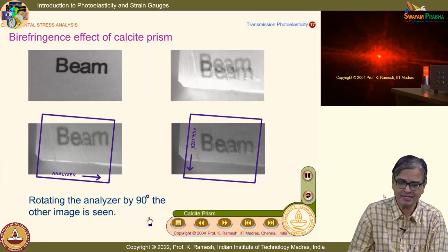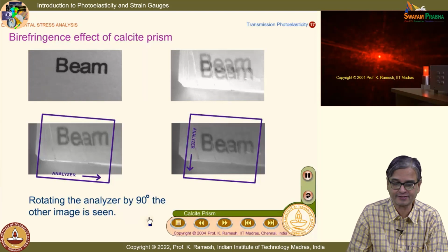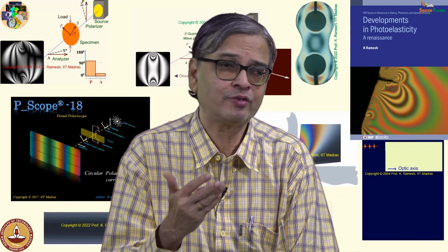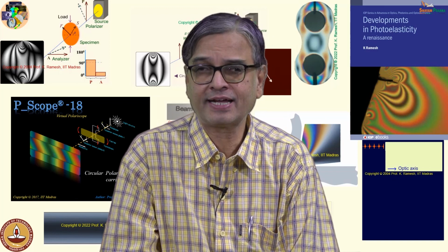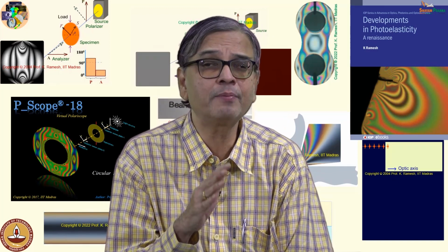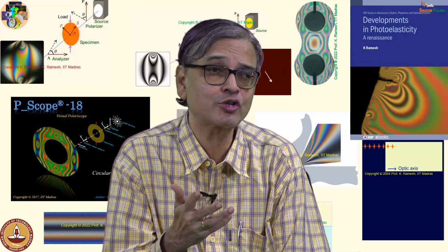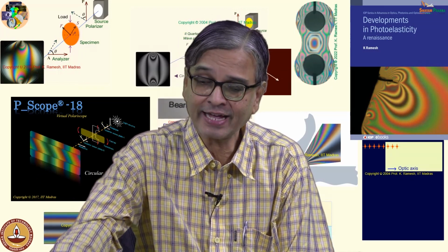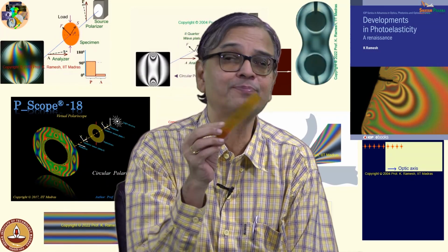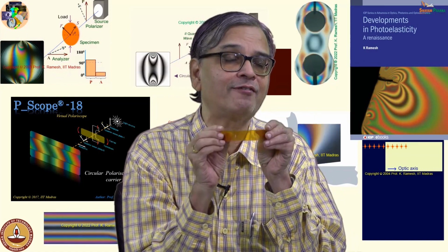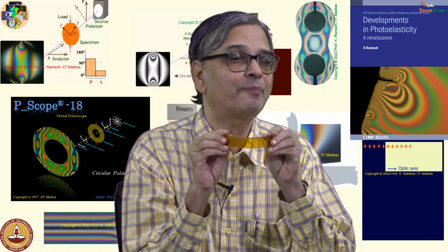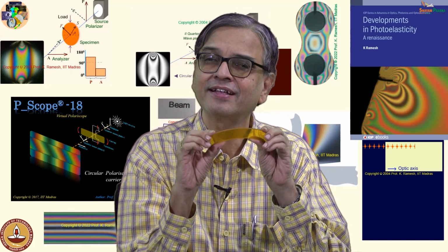Now, we will see what is useful in photoelasticity. You all know when you take a crystal, it has an optic axis. See, a crystal is permanently birefringent. So, that is not useful for photoelasticity. Whereas, when I have a polymer like this, polyurethane, it is easy for me. I do not have to be a Superman to apply the load. I can easily bend it, fine.